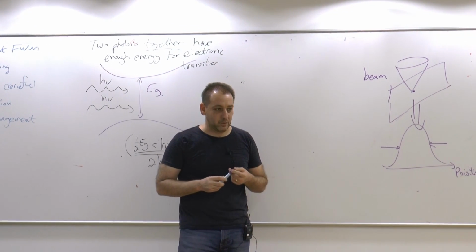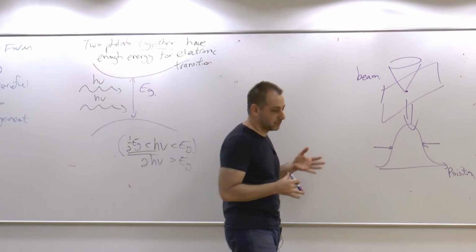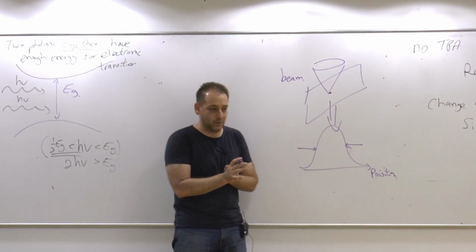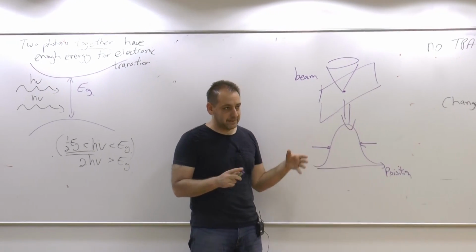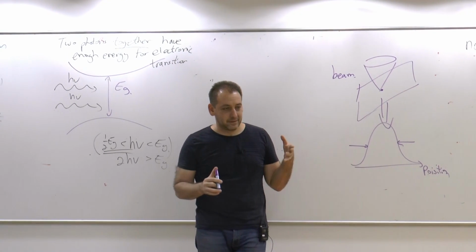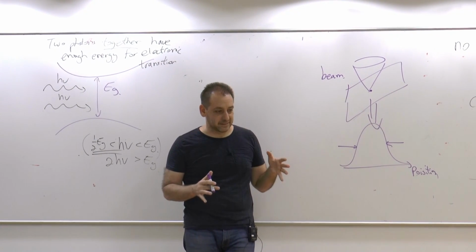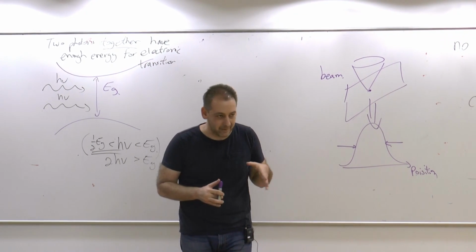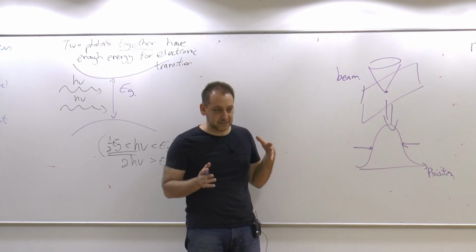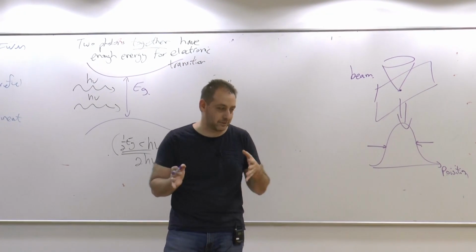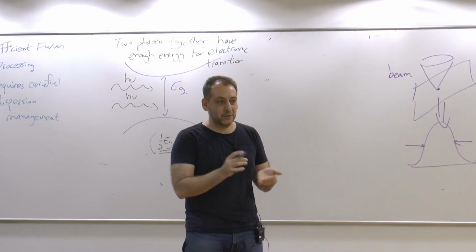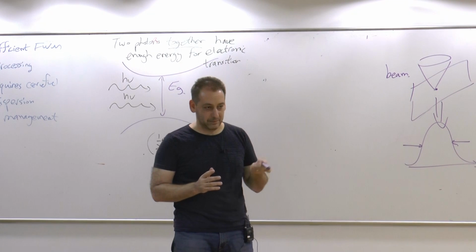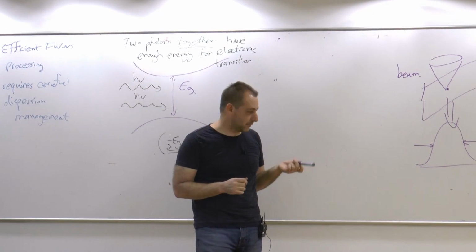This is why when you do photolithography in clean rooms with mask aligner or laser writers or whatnot, typically the features that you can define are hundreds of nanometers, give or take, sub-micron, maybe even a little more than 1 micron, because you're using light and you focus light at the diffraction limit, you get to the scale of the wavelength, give or take. If you want to go much lower, you go to electron beams.